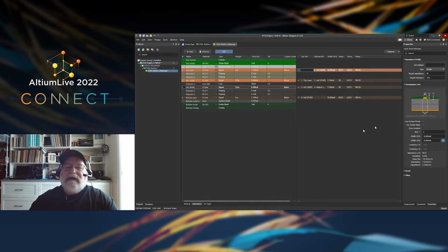So let's take a look at the characteristic impedance of a signal line that's on this layer. And so here it is on layer 1, and we're going to turn off solder mask initially, and we're going to turn off the surface finish. This is a different metal layer, a coating, HASL coating, for example, or plating on the top layer, with a different thickness. We're going to turn that off as well, but we have the option of including that. And so it's just bare metal.